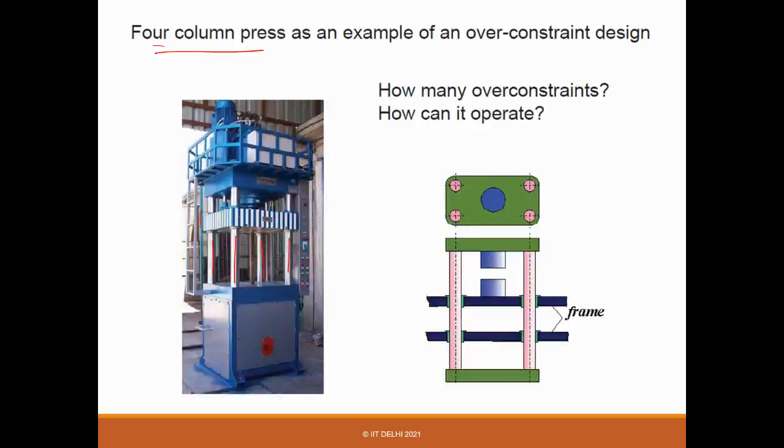the middle one actually moves up and down. So if you just draw it here, what do you see? There is a frame and this thing moves up and down, and then maybe you have some piece here. So there is a movement against each other, right? Suppose the frame is fixed and this is the thing which goes up and down. So what do you realize? That's only a one DOF system. This is the degree of freedom you want. This should be able to translate.